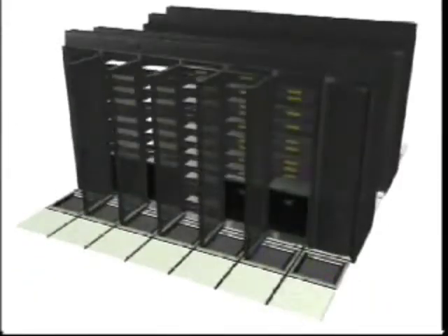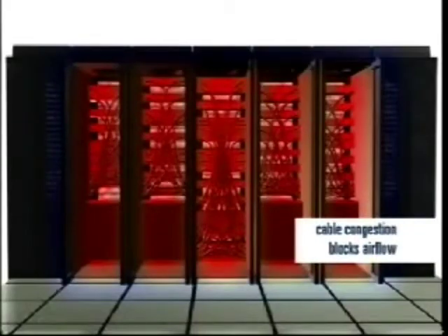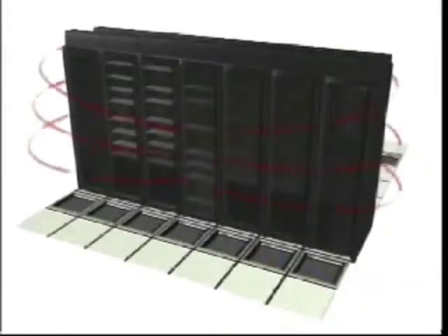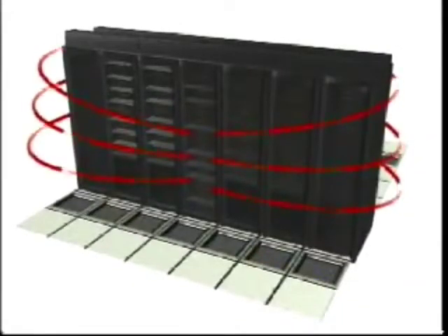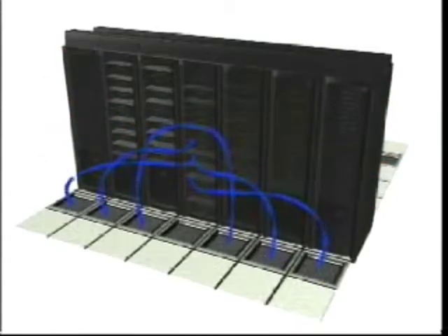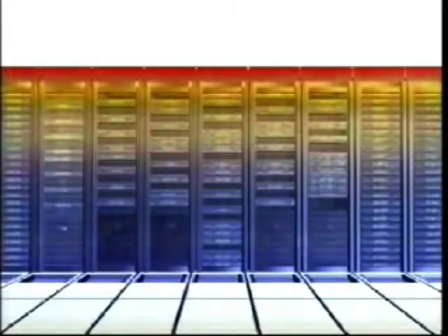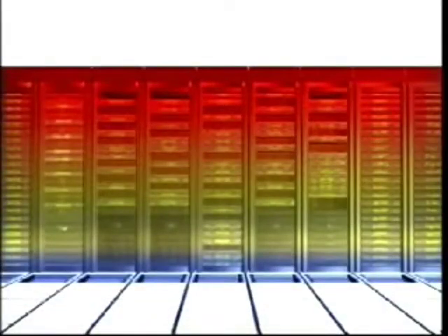6 months later, it's time for another IT refresh. Even more equipment is added, leading to higher power densities as well as cable congestion from additional network drops and power cords. Air recirculation increases. Because the new, denser servers cannot draw the necessary airflow from the raised flooring for proper cooling, they must pull the required air from another source. The air temperature across the entire room also begins to rise. As more heat is generated, the curtain of hot air at the top of the room is lowered closer to the rack inlet. The cooling situation in the data center becomes critical.